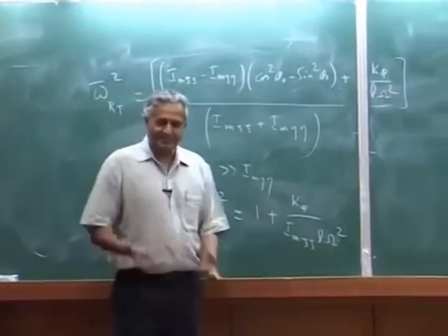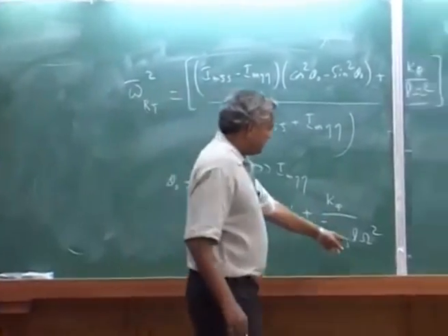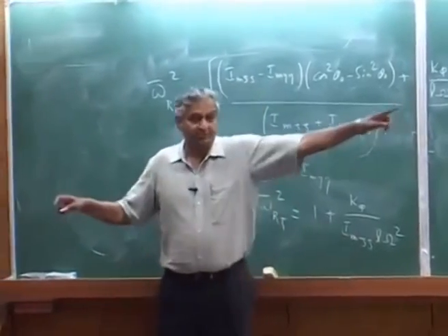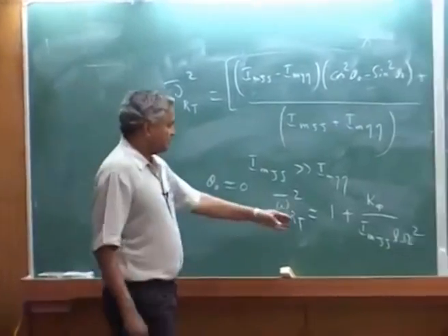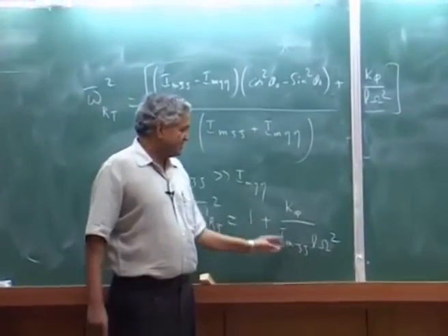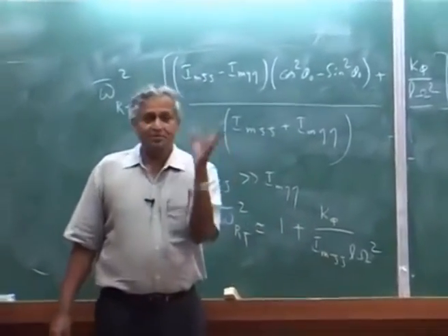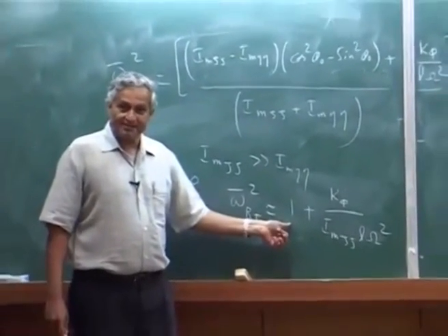That means you can take it as the blade torsional inertia, because I took this constant L into this, it will be the torsional inertia of the blade about the quarter chord. And you have it non-dimensional with respect to omega square. This is like a simple torsional spring, and this is due to inertia.